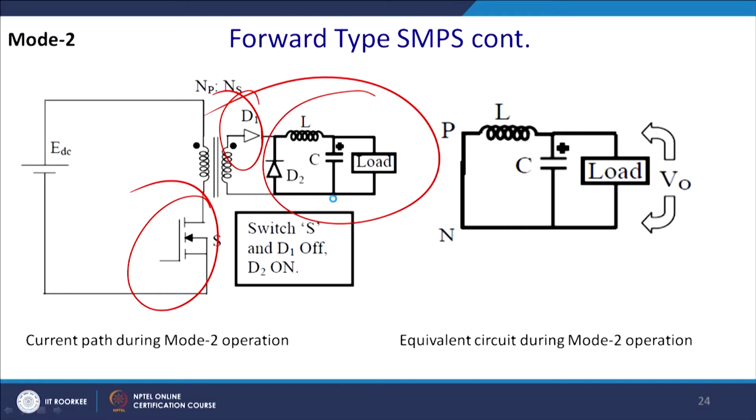Same in the case of the forward converter: if you increase the duty cycle beyond some limit, resetting the flux is also a challenge. We have solved a few problems in the forward converter, because the stress across the switch here is quite low.